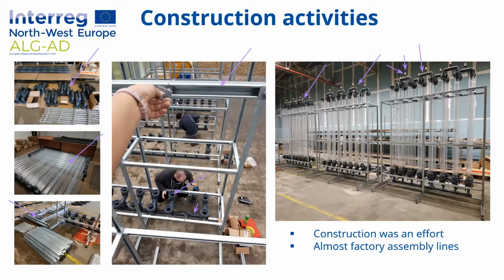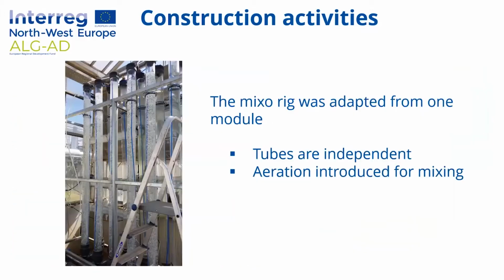So when the system is initiated, obviously the tubes are full of air. Once the liquid starts pushing through, these valves allow the air to be released out of the system, and then the whole serpentine reactor can be flood filled with liquid with no issues in terms of getting the air out of the system. So they were an upgrade, if you want, from previous designs that we'd made, and they worked really, really well.